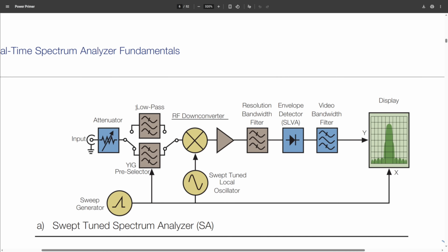Well, we have them because people realized that it's really hard to make a tunable filter that can also be swept, especially with old school analog electronics. So instead of relying on complicated mechanical stuff in order to tune a filter and also sweep it, people decided that it's a lot easier to have a spectrum analyzer that is only sensitive to one frequency basically, and then using a mixer and a swept local oscillator, you can down convert the input to that frequency that the spectrum analyzer is sensitive to, and this way you get a spectrum analyzer and the effect of a swept filter without actually having a swept filter, if that makes sense.